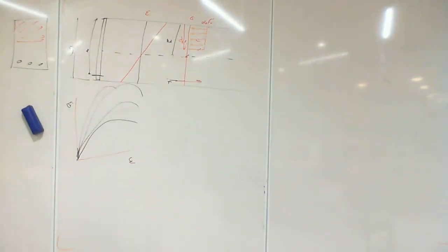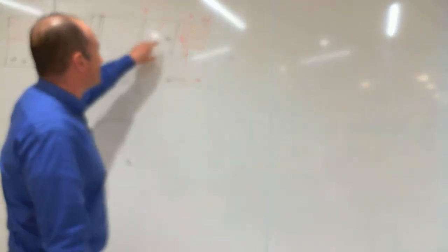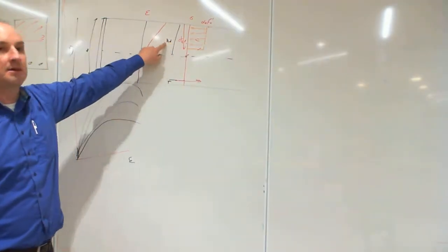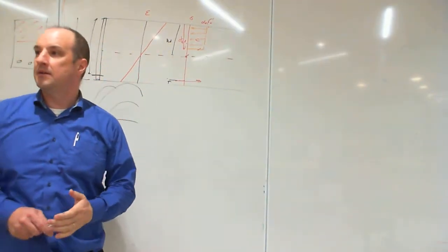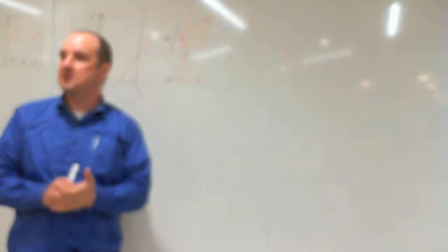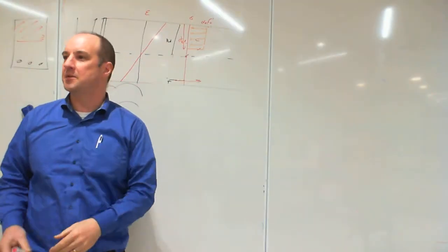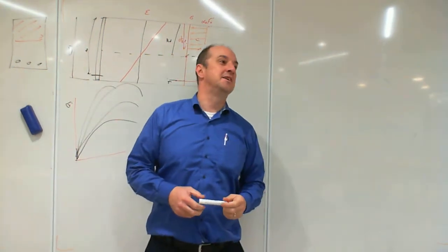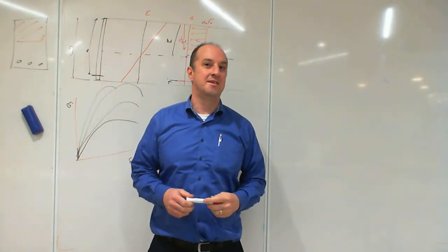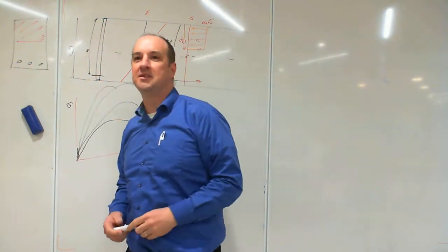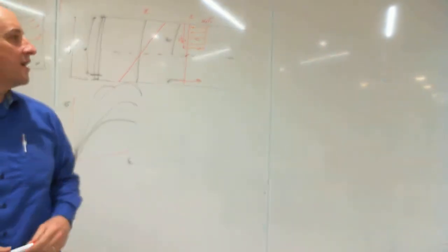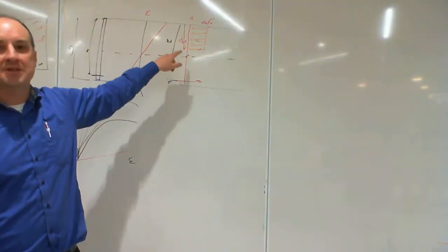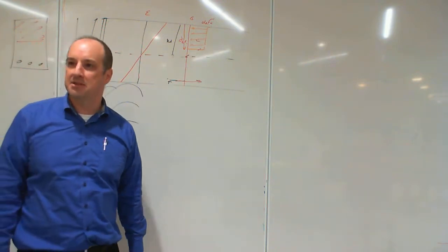So far, so good? All right, what do you guys know about Ku? It's less than 1, yep. Can someone tell me what the maximum value you should design with is? Anyone? 0.36, very good, yep. In the current code, Ku is not allowed to be bigger than 0.36.